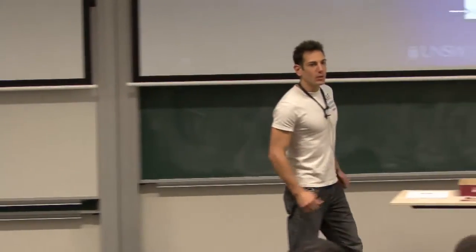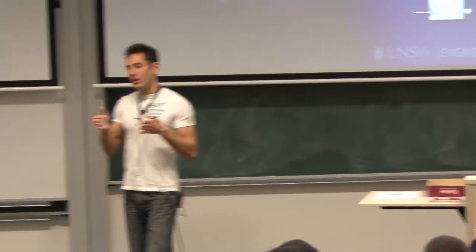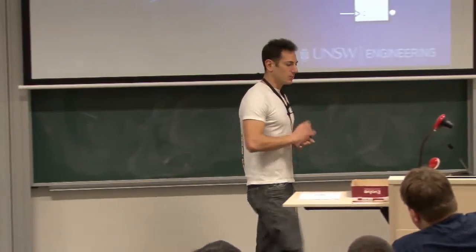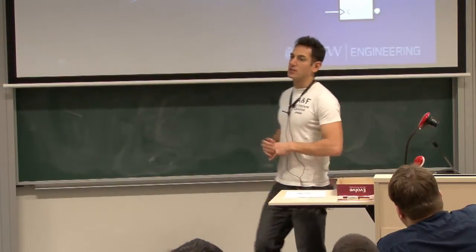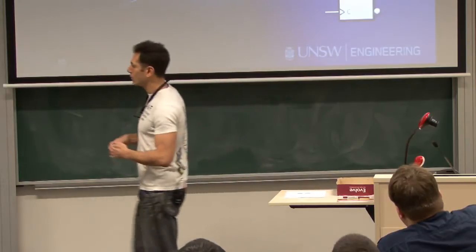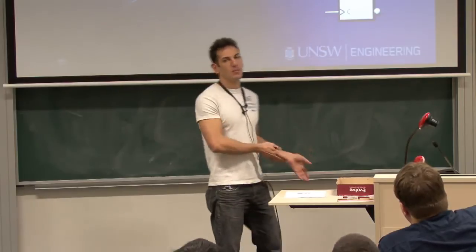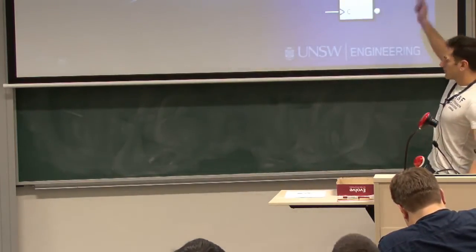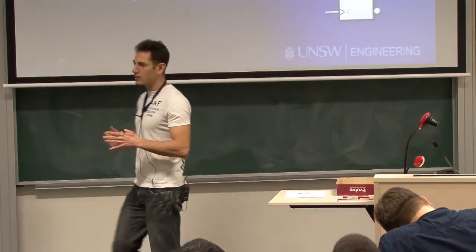Capacitance. When you start having layers of wires, then essentially you're creating capacitors in them. The thicker your wire is, the more capacitance you actually add into the chip. The more capacitance, the more you have to charge and discharge it, the slower your propagation becomes. So although you minimize the resistance, now the capacitance is a problem. So you really have to very delicately design those clock paths to match exactly.